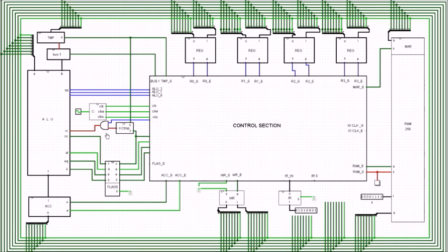So now in order for the carry in here to go high, it'll only go high whenever we're performing an ALU instruction, and it'll only go high at a particular point, and the point is going to be given by this input here, which is at stage 5 of the ALU instruction. So really at the same stage as this flag set instruction, which we talked about just a minute ago.